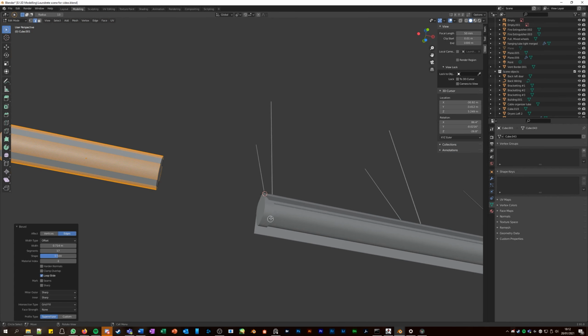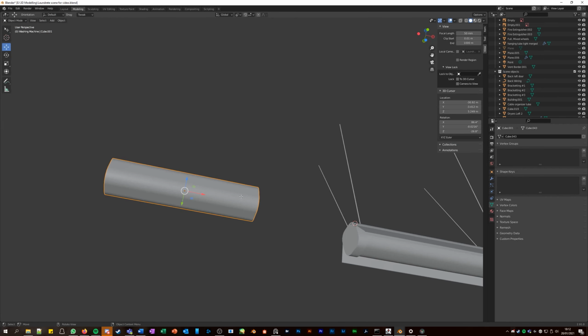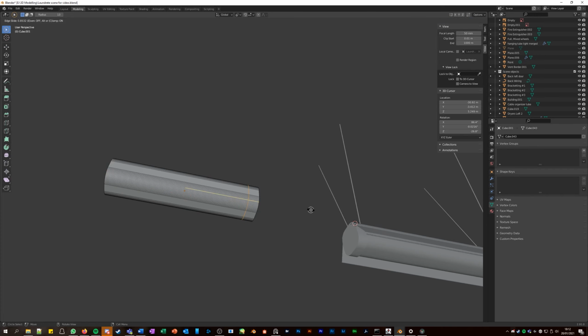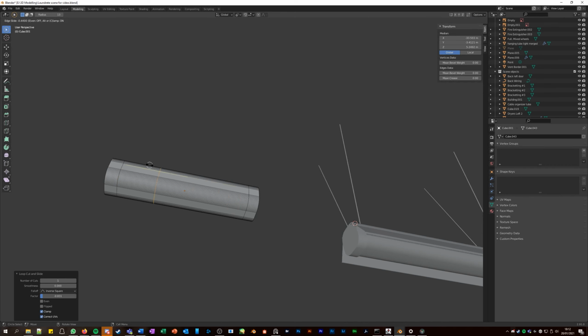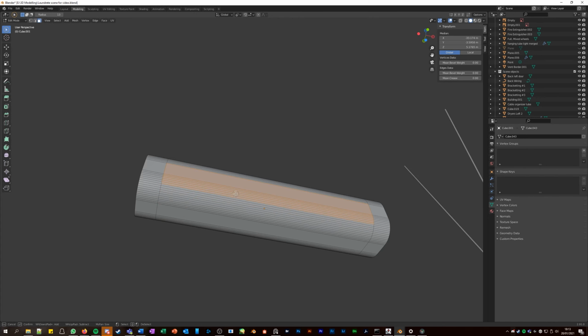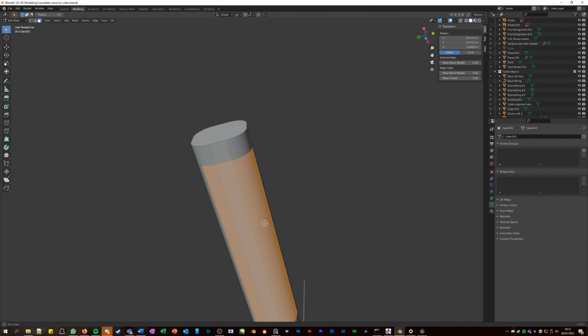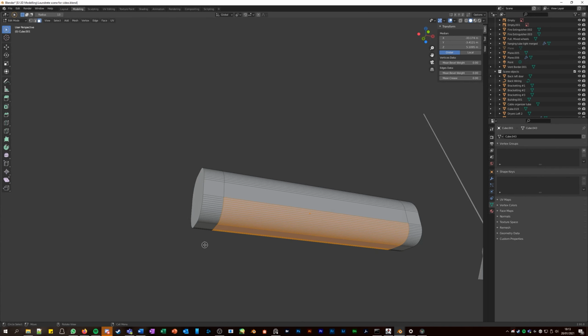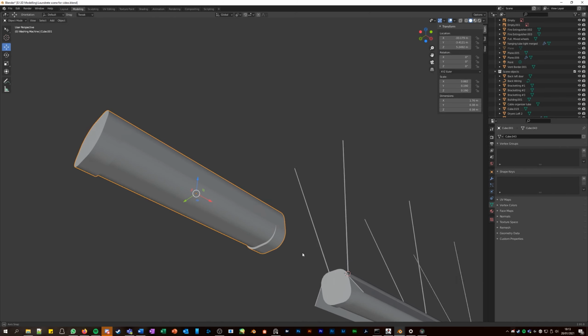With the edges, I added a loop cut on either side. About there. I think I used numbers up here. If you go into item, you can see in the top right under transform, there's a number for where it is. I did it properly to evenly space on either side. And then took these bottom faces. Okay, took them and extruded them inwards to add a bit more depth, so it's not as smooth.